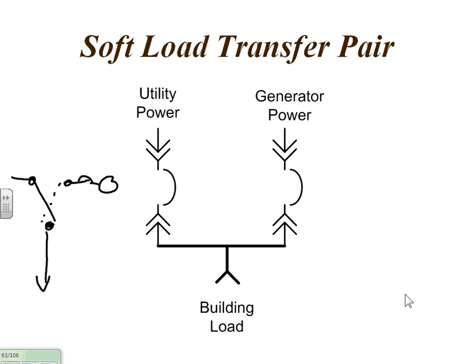Does that come with the generator, or is that like the secondary? Yes, it can be either, but typically it's just the generator battery. This is a pretty simple system. Once it sees it here, they can even use a relay that's on emergency, and there are no batteries. The relay drops out, it's a normally open set, and it closes. That tells the generator set to start.